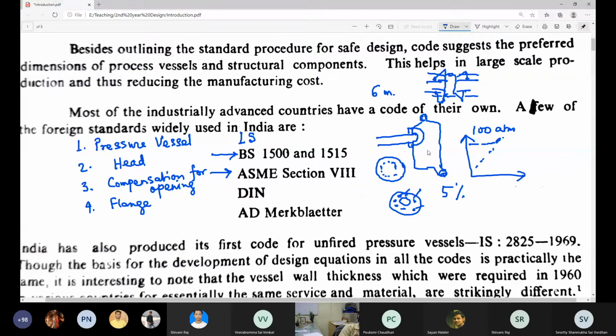The gasket is asbestos or some such gasket material. As you put pressure, as you tighten the bolt, this gasket material sort of flows over the nook and cranny of the surface, because the surface has certain roughness. So this gasket is a soft material.